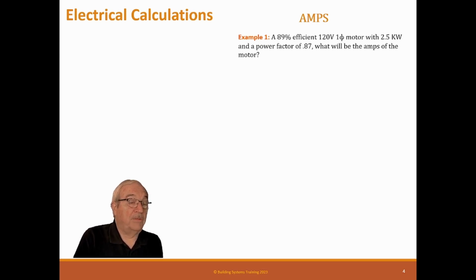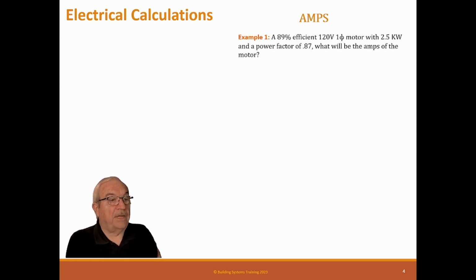Okay, now if you're doing a calculation from a drawing, or you're doing a calculation from measurement of the field, power factor may be difficult for you to figure out what that is. You can measure power factor, but you have to have a power quality meter to do that. You can't get power factor from a regular handheld voltmeter. So power factor can be somewhat difficult. Now some machines will list the power factor on it, but that's the design power factor of the product, like a UPS or something. So what you need to do is try to guess what it is.